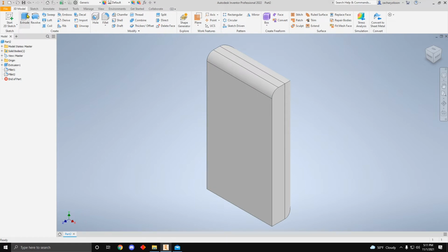This is where it becomes different. Now you have this shape, right? And when you go to start a sketch, you can click on it, but then nothing happens. But when you float over this, you can start a sketch not on a plane. You could start it from a plane, like when grabbing this origin key over here, and go to whatever plane you want.